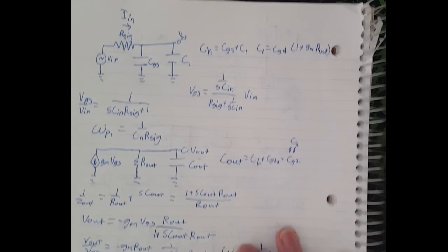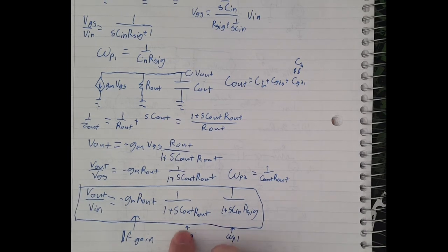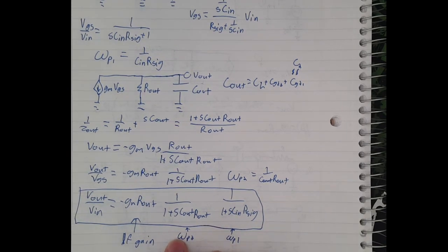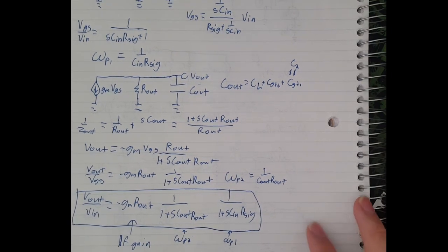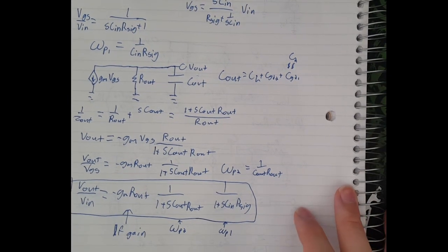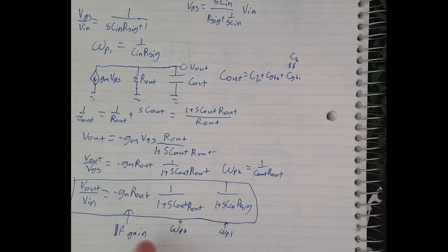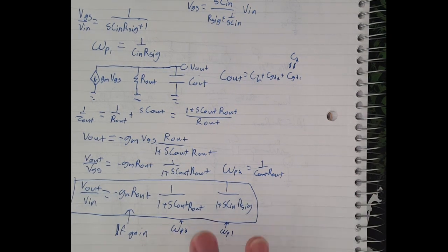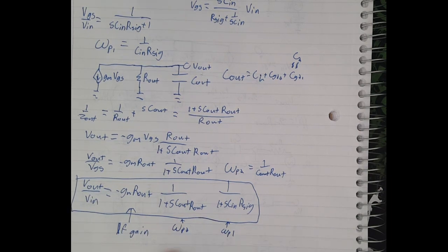And if you're at that high frequency, these two poles have already attenuated your signal significantly. So the fact that there is a 0 there does not affect it that much. If you're doing really high frequency stuff, you will have to analyze this, and that requires you to do a full circuit analysis. But for this class, doing node pole is fine.